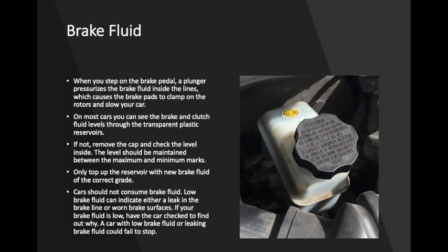Brake fluid. When you step on the brake pedal, a plunger pressurizes the brake fluid inside the lines, which causes the brake pads to clamp on the rotors and slow your car. On most cars, you can see the brake and clutch fluid levels through the transparent plastic reservoirs. If not, remove the cap and check the level inside.